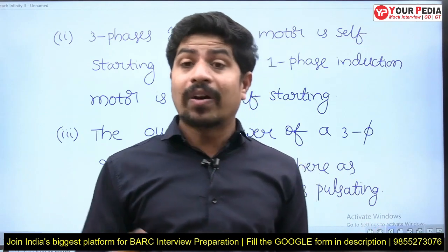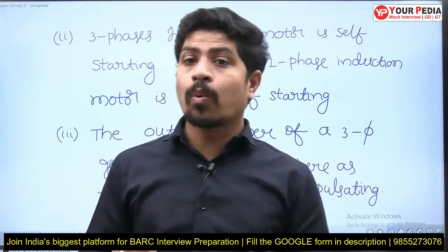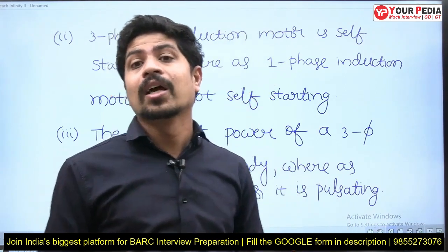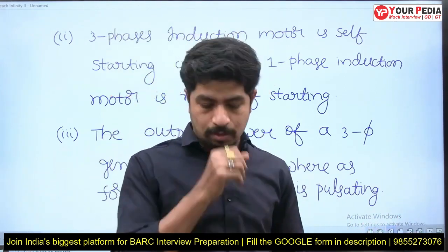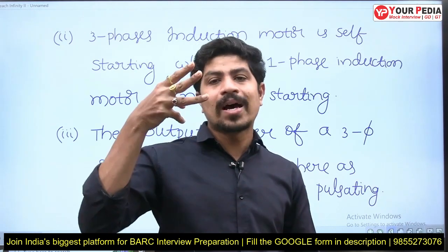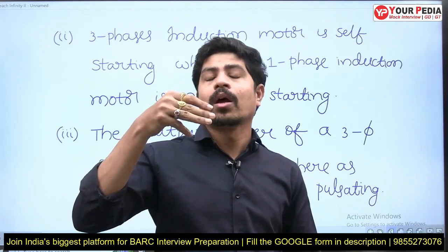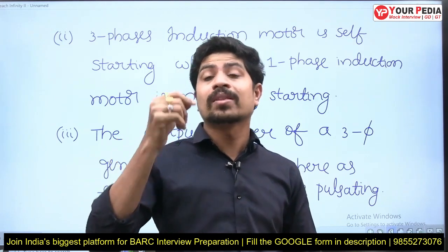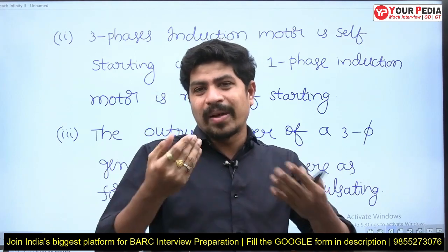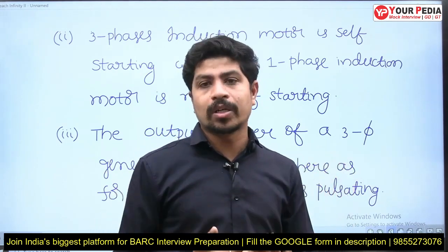And for three-phase transmission, the amount of material required for the same amount of power transfer is less when compared to single-phase transmission. Yes, that also you can prove. For a three-phase balanced transmission, no separate return path is required, but for a single-phase transmission, a return path is required. So like that, by taking some examples, you can prove all these points to the interviewer. Thank you.